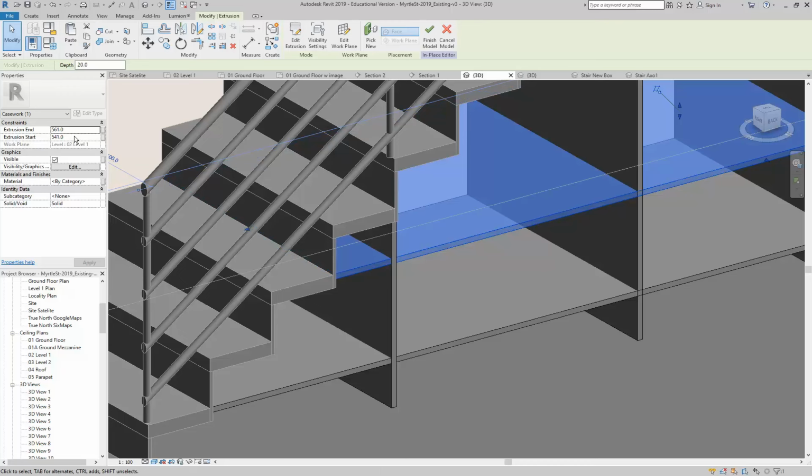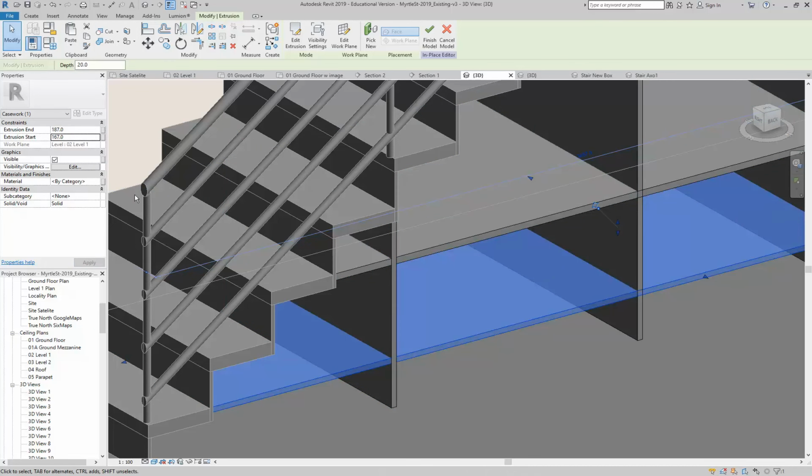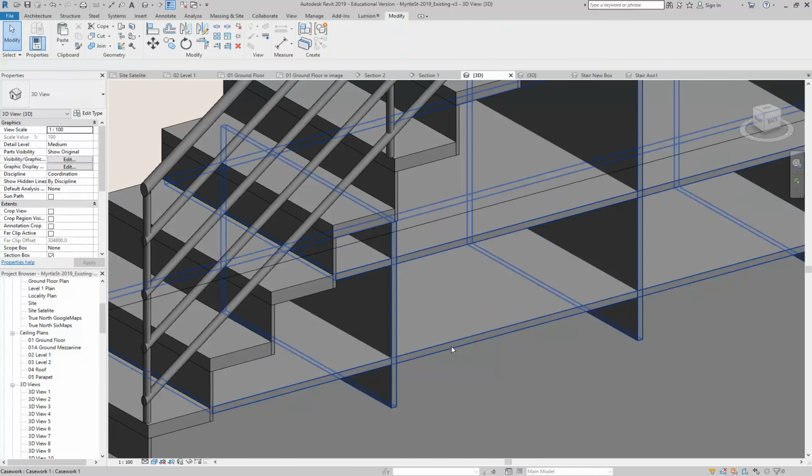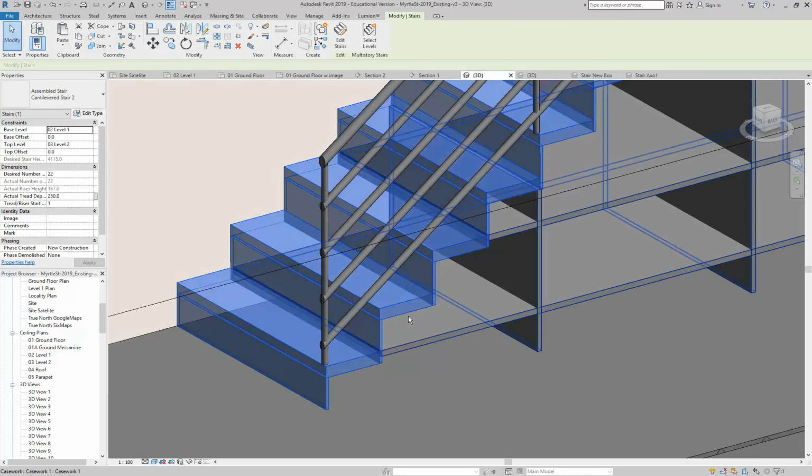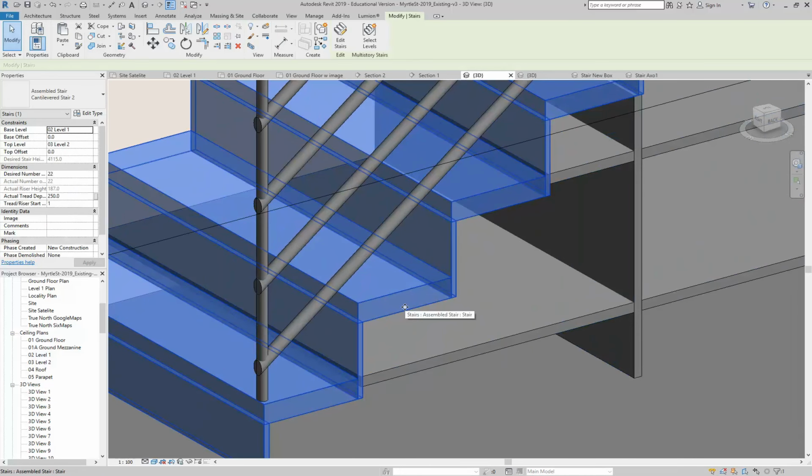So here it would be, if it's 561, another 5mm down from 541, so 536. And this one is, again, another 5mm down, so 162. So I'll finish that. We'll join it all later, but I don't even mind having the joins. All right, so now I want to make my steps the same thickness, the treads.